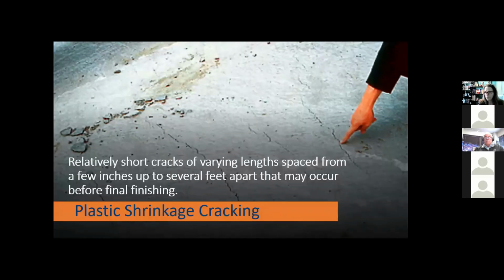So I think it's very important that we understand patterns of cracks. There's a difference between an isolated crack and ones that are map cracks, whether they're transverse to a joint, whether they're longitudinal, if they're isolated, if they have feathered edges, if they're through cracks. All those things tell you a story about how the concrete is feeling. And the concrete definitely has some strong feelings about cracking if it's in the wrong location.